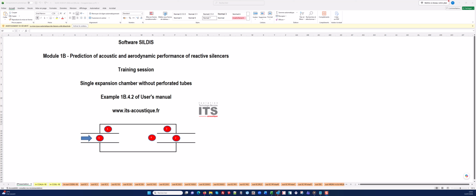The expansion chamber is made of 5 elements numbered 2 to 6 from the downstream side towards the upstream side, with number 6 being a uniform tube for inlet, number 5 being an extended inlet, number 4 being a central uniform tube, number 3 being an extended outlet, and number 2 being a uniform tube for outlet.